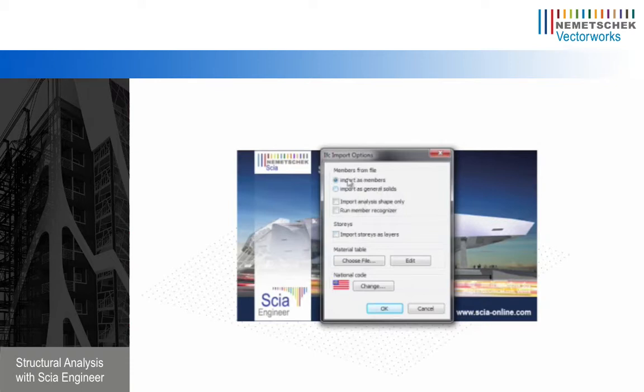The most important being whether we import as native Scia members or whether we want to import the entire model as general solids. Typically, when I get a model from an architect, I'll start by importing it into general solids because the model is traditionally going to contain all sorts of additional objects that I don't really need to be concerned with. Things like floor coverings, window mullions, doorknobs, light fixtures, and so on. So we'll select Import as General Solids.